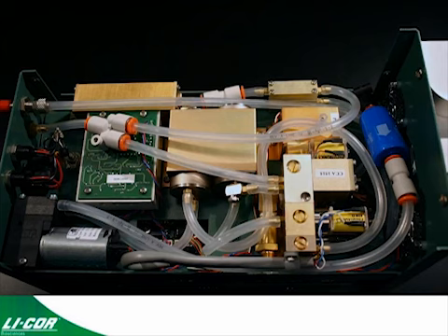The flow path is now complete, and it is different from the standard flow path as the instrument comes from the factory. This allows for control of the CO2 concentration inside the chamber at very low concentrations. The new tubes can be removed from the system at a later point if you so choose, and the system returned back to the standard flow path by simply reversing the configuration and putting the system back in the flow diagram as shown in an earlier slide.